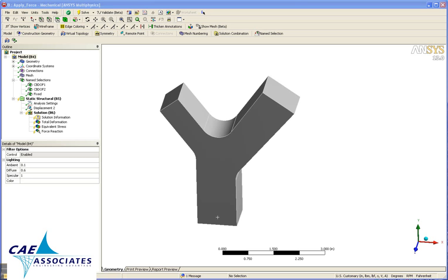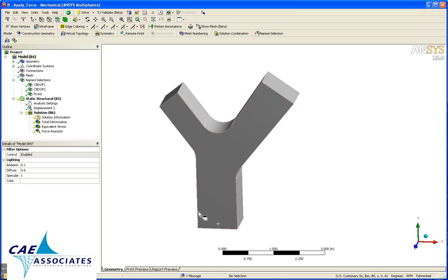This demo will show how to use the scripts that will run the force-based submodeling instead of using the traditional displacement-based. So you need to initially have some problem that will have, in this case, a part that's fixed on the bottom surface, and then some locations here that represent the submodel, but there are some forces and maybe moments that are going to be applied to these surfaces instead of displacements to maybe all three of these locations.